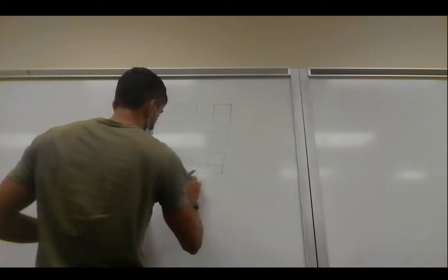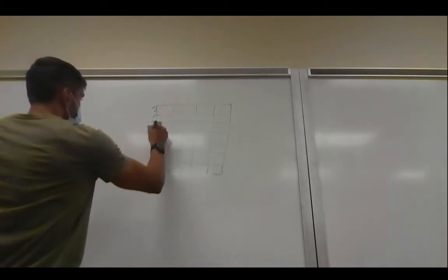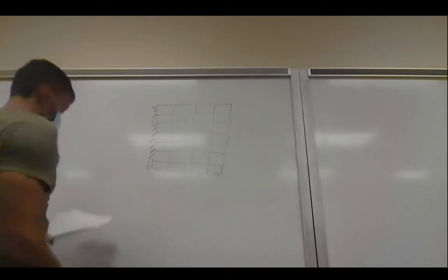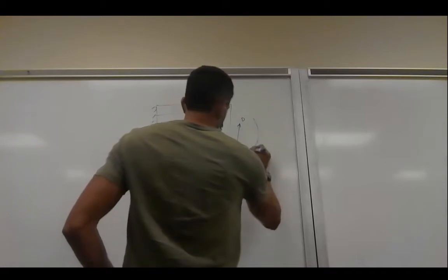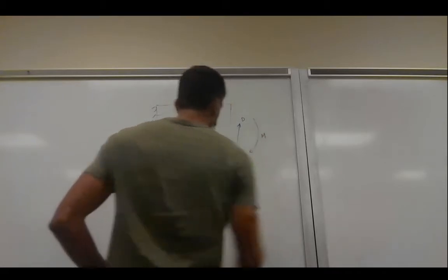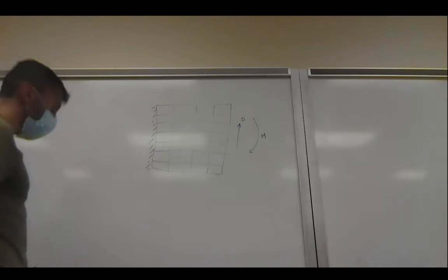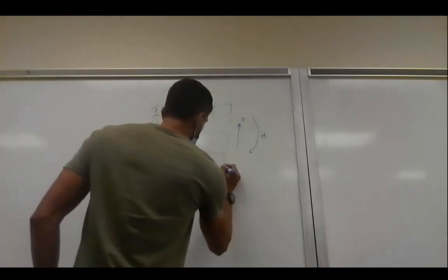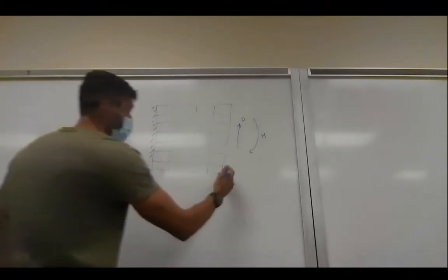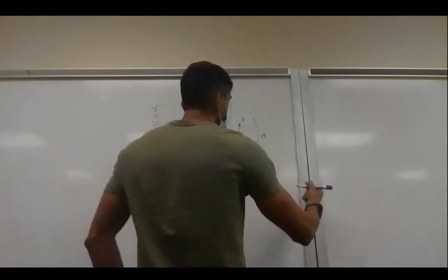This is our problem. This side is fixed. And on this side we have two forces. We had a shear force, in this case called D, and a moment called M. So what I also said is, okay, well, you have basically these stiffeners, stringers, whatever you want to call it, they're booms.